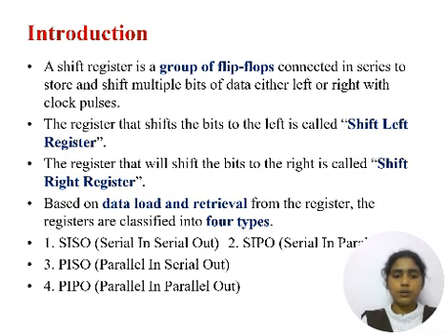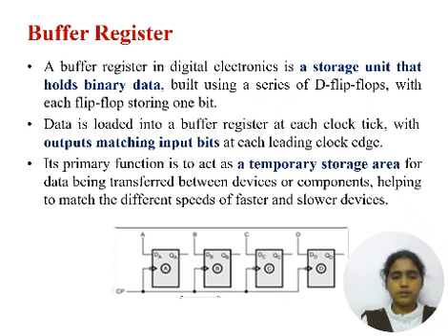Based on data loaded and retrieval from the registers, they are classified into four types: SISO register, serial in, serial out; SIPO, serial in, parallel out; PISO, parallel in, serial out; and PIPO, parallel in, parallel out.